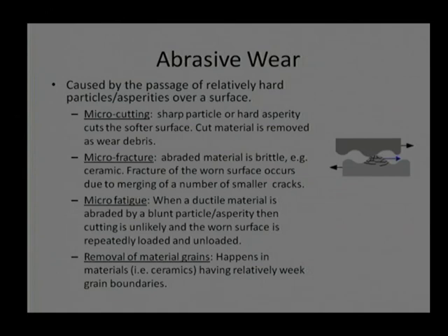What will happen because of relative motion? The asperities are blunt, they are not very sharp, they are not conical, maybe we can say these asperities are spherical in nature. So, it is going to cause stress on the surface again and again, which turns out to be cyclic loading of the asperities, load and unload, load and unload. That will cause some sort of crack formation in the asperity itself, or maybe beneath the asperity also.